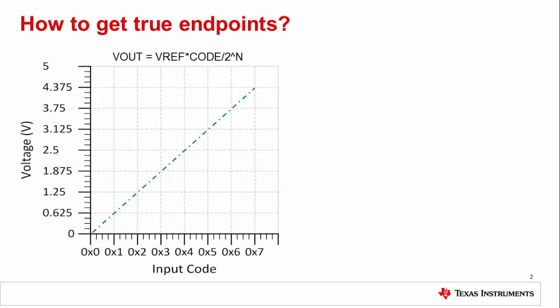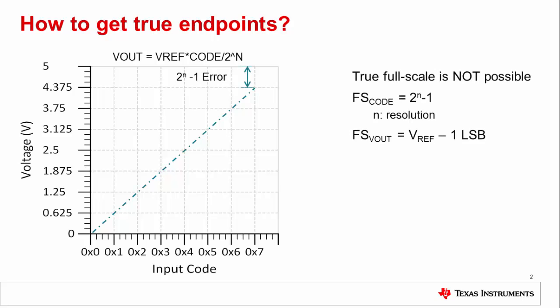Now to true non-idealities. Full-scale and zero-scale errors are not part of the ideal DAC model. In fact, these errors don't relate to the DAC architecture itself. Rather, they relate to the output amplifier that the DAC core uses. These are the same errors that you expect to see on any discrete amplifier. Therefore, the same solutions applied to amplifiers can be implemented here.